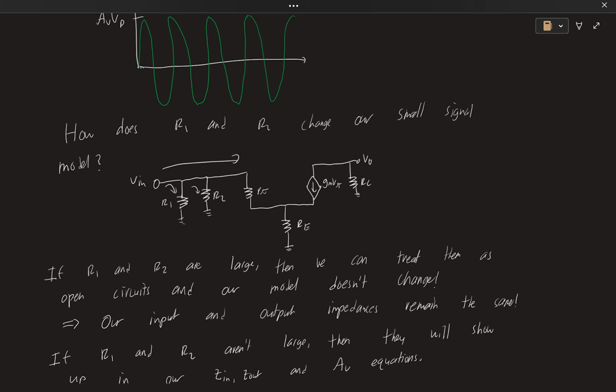The main thing we care about is getting the right gain. And as we'll learn in later hardware lectures, if we have something that looks like 50 ohms, and then we connect it to something that, if you use the normal values of R1 and R2 in the 10,000 range, you might get like 45 or something like that, you're going to have an impedance mismatch, which means you're not going to get maximum power transfer from network 1 to network 2. Right? If network 2 looks like 45 ohms, network 1 looks like 50, you're not going to have an optimal power transfer.